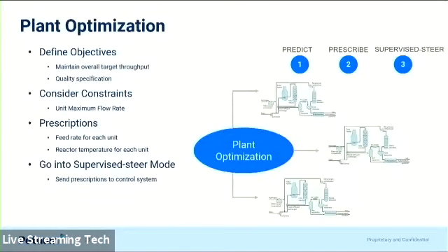And then this one, this is another great benefit of deep learning, is that typically models that are just physics-based for multiple units are going to be very hard to do, right? You need to eliminate some variables, make some assumptions, and of course you can create a linear model that will do something. But now what we are doing is that we are looking at the data of the end plants. Then we create a very big model, inferentials, and then we do the optimization in order to coordinate the operation of the 3 units. We have a big optimization function that is looking at the revenue of each one, and it's going to find what is the best pace that you need to run at. All right, so that's RTO type of projects with AI.